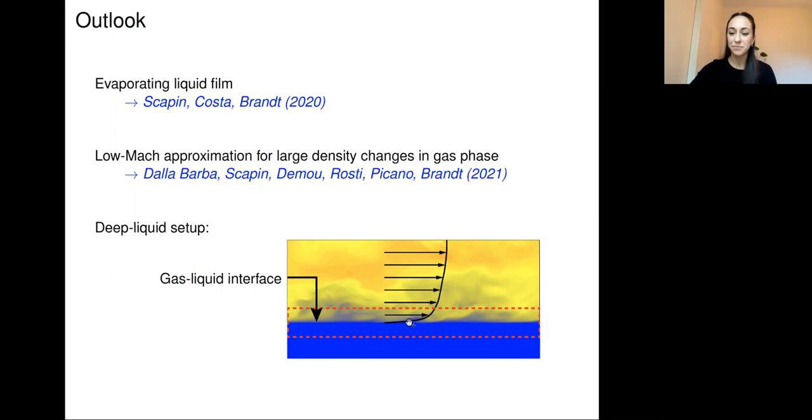A next simulation I would love to do with this code, because it's a lot cheaper than these other codes, would be to double the streamwise and spanwise directions, just to see what comes out. I don't think there'll be big differences in the physics. We don't get very many measurements of that spanwise dimension, so in order for it to be better converged, it would be good to repeat this in a bigger domain. Thanks.